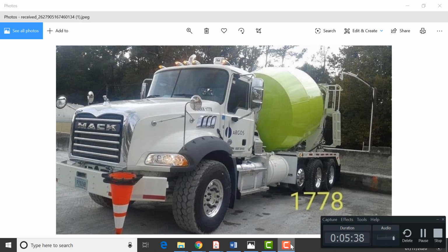Weight of SSD aggregate used per cubic yard from the design mix. A. This calculation takes moisture content as a percentage of aggregate weight and turns it into a measurable quantity in pounds or gallons, to be used in the adjustment of both batch water and aggregate quantities.